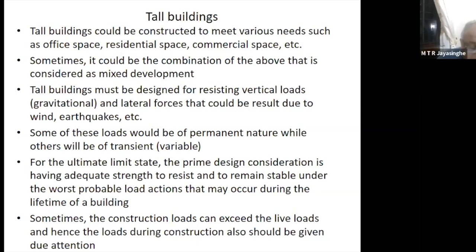And if you have ensured 20 to 25 millimeter cover, all the steel in the slabs will be very safe. They will not undergo any deterioration. And with that, even with 20 millimeter cover, you can easily say you have a slab that is not going to fail easily.